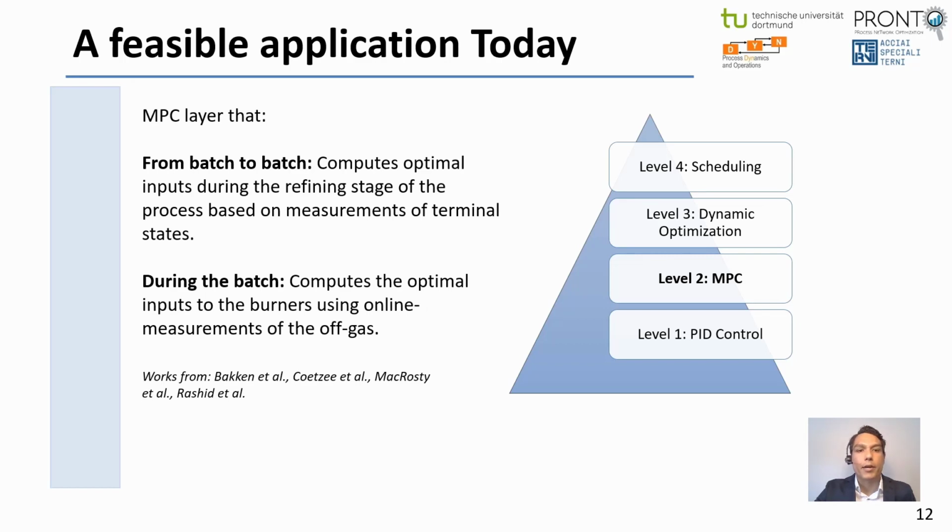Finally, in the MPC layer, one can perform two types of computation. On the one hand, from batch to batch, one can compute the optimal input for the oxygen lancing during the refining stage, taking into consideration the terminal measurements of the temperature as well as steel composition. And on the other hand, one can use online measurements to optimize the efficiency of the combustion process in the oxygen fuel burners. Some representative authors are as I show here.